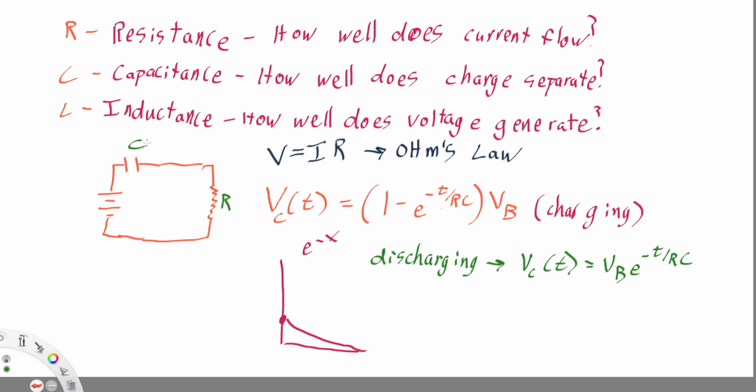So you turn it off, and you're not feeding any fresh power into it, but the capacitors still have electrical energy stored. You need to give them a chance to discharge, so the system is fully off before you restart it.